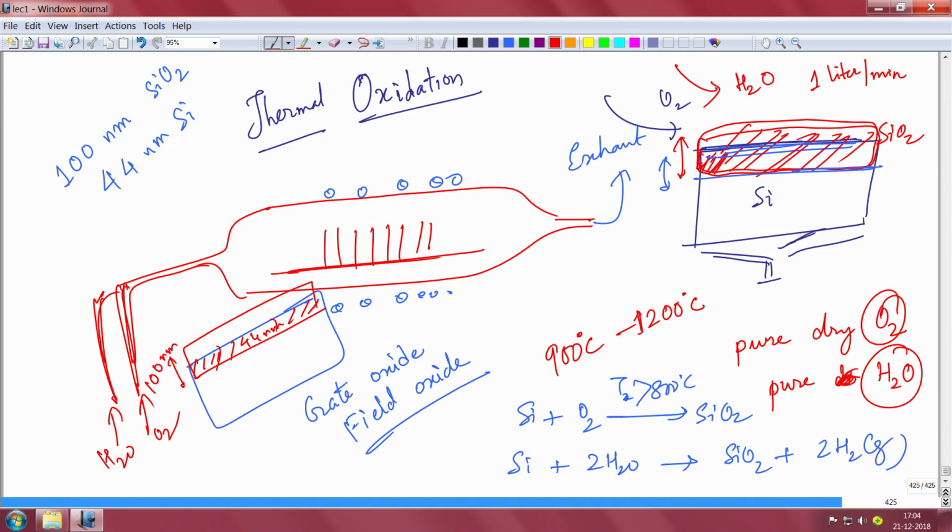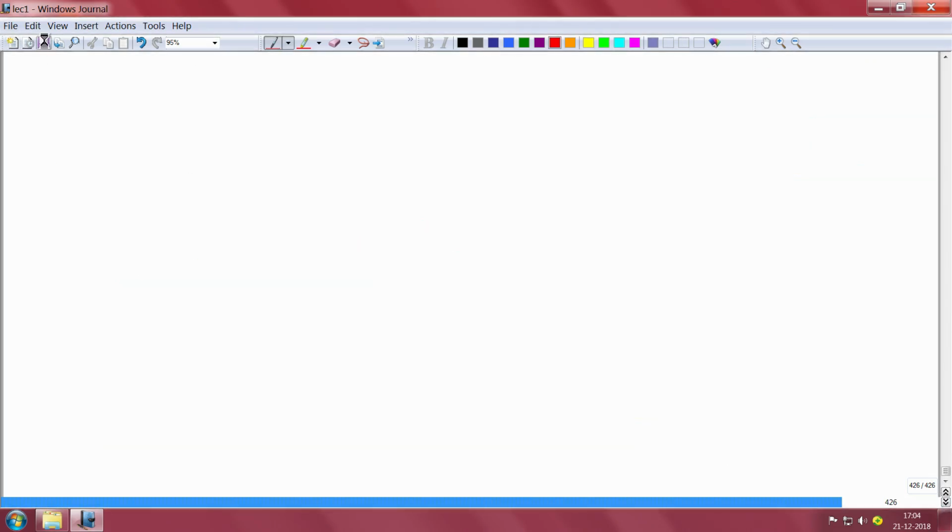And this oxidation process has a lot of mathematics involved, like you want to find out the rate of oxidation, there is Fick's law, how much surface concentration you need and all these things, which you will skip carefully. For thicker oxide, typically if you want to grow field oxides, you use wet oxidation, and if you want to grow the gate dielectric, a thinner oxide, you typically use dry oxidation. Now, next we come to doping.